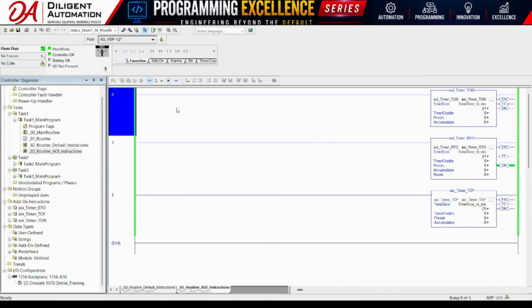By creating our own versions of the TON, RTO, and TOF instructions, you'll gain a much deeper understanding of how these timers actually work internally. This approach will help you think beyond simply using an instruction. You'll begin to understand how automation engineers design and implement instruction logic. Once you understand the internal working principles, you'll be able to develop your own reusable function blocks and add-on instructions for real industrial applications. That's a skill that distinguishes an automation engineer from someone who simply writes PLC code. So let's get started.